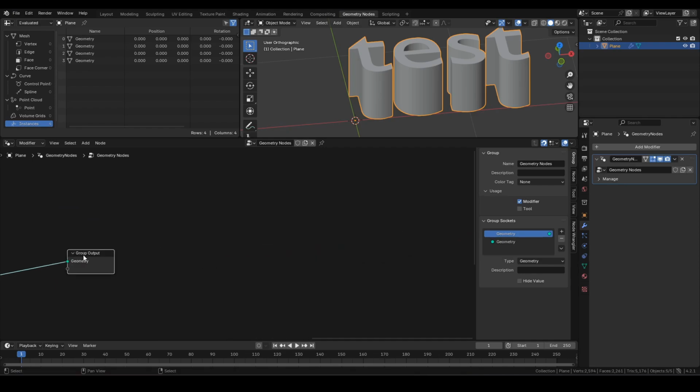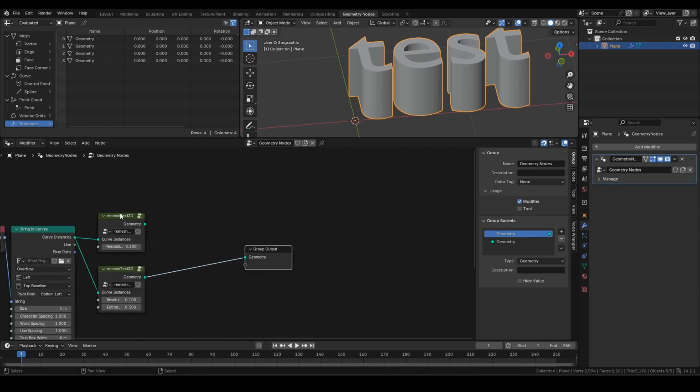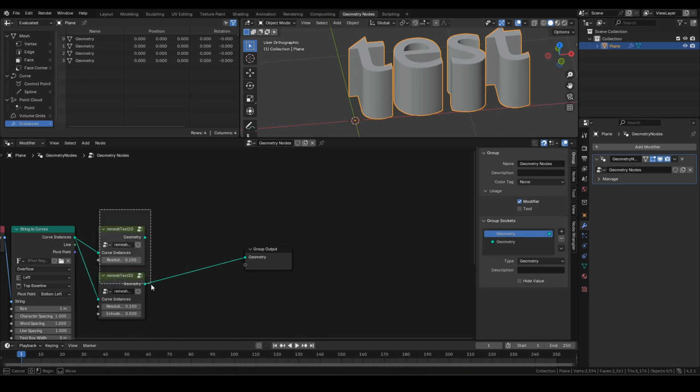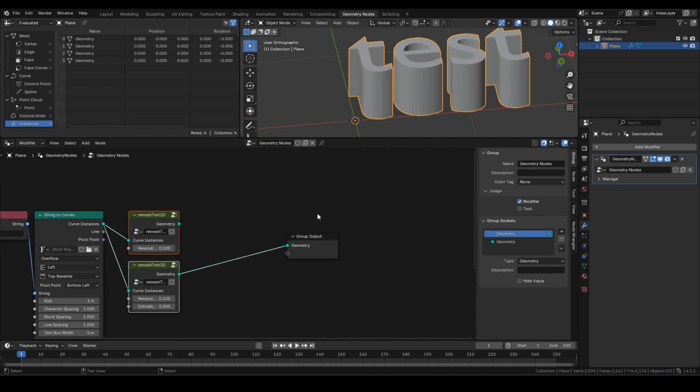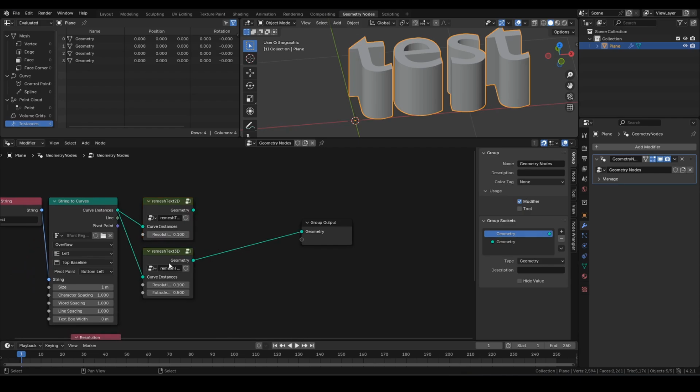We aren't going to be making any particular effects today. The purpose of this video is to make these two node groups. So what I'm gonna proceed to do is turn them into assets. So right click on this shield and go down to mark as asset for both of these node groups.